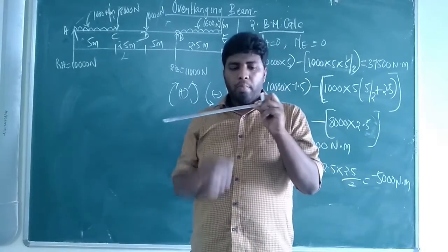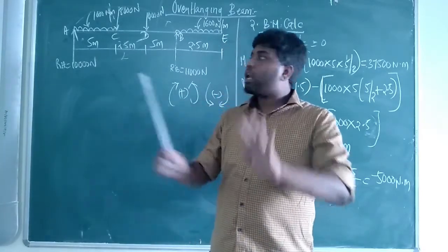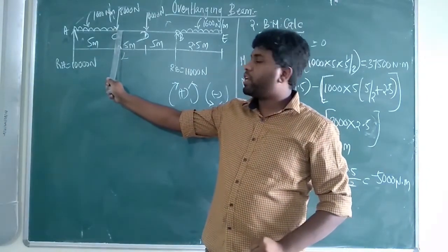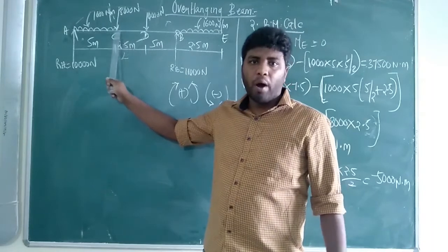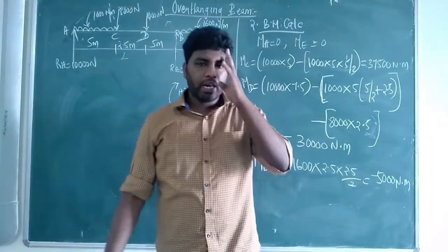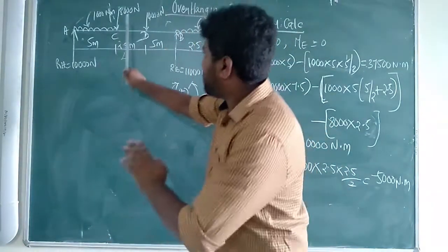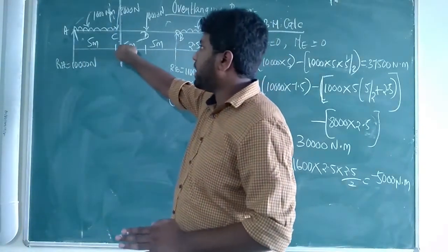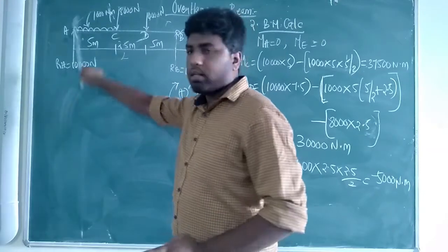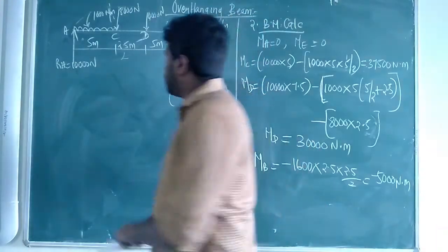Okay. So if you are going to consider bending moment at point C, if there are vertical loads, you should not consider that point load because that point load will never make a bending on the left of C. From the left section, what is there? C, UDL, this is there. Understand?